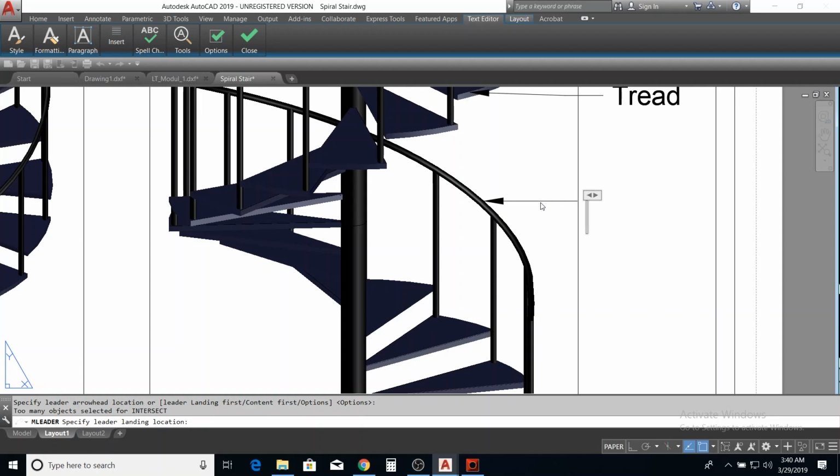Let's hit shift percentage. Then the symbol of diameter appears. We have so many of these shortcuts. For degree, it seems percentage for degree. So maybe in some upcoming videos, we will take time and go through some of these shortcuts. For now, percentage for diameter, 38, 8 mm, right?